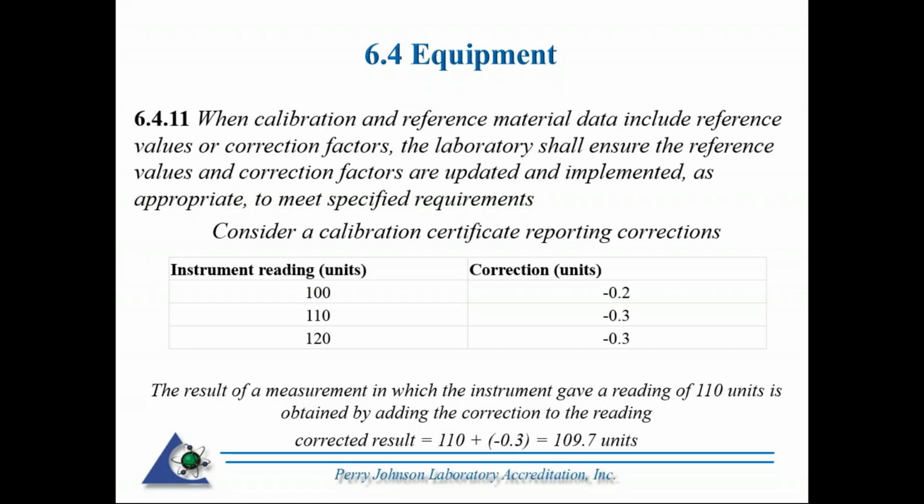If you're utilizing those correction factors, they're often used in software. So when the calibration report comes back, if that correction factor is used in any software, it needs to be updated. That report needs to be reviewed. If there's a change in the correction factor, it needs to be updated. If you're using them in handwritten data sheets, that form may need to be updated to reflect the change in the correction factor.